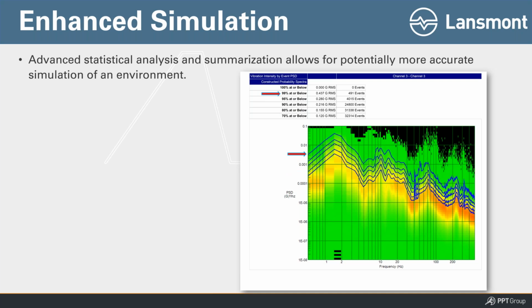And as you see, as I scroll through that, up at the top, it's summarizing what the GRMS intensity is at that level and how much of the transport in terms of events over here occurred at that level. And if you think in our examples, it depends on what the time of your events is, but if they're 2-second events, I can quickly do math on this, right?